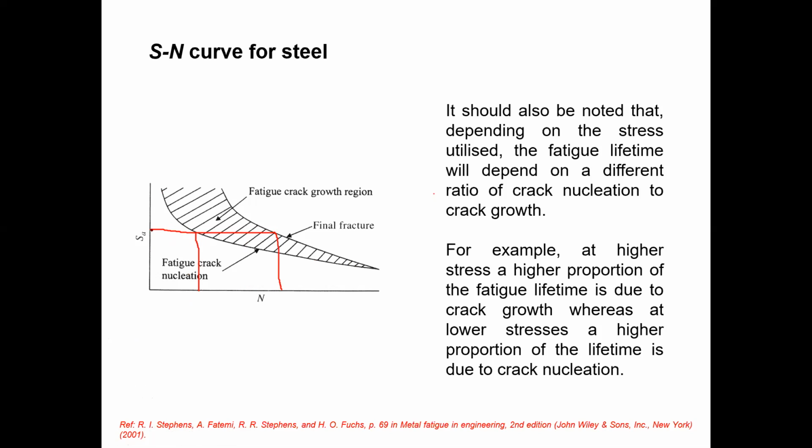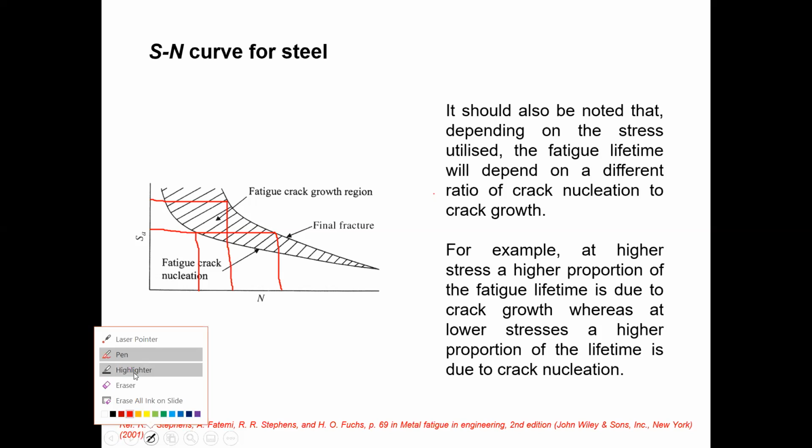Very important to keep in mind: if you apply a much higher stress, crack nucleation happens very quickly at the upper boundary. At the lower boundary, the significant thing is not crack nucleation but crack growth, which happens suddenly after nucleation somewhere here. You will understand what I'm explaining later.